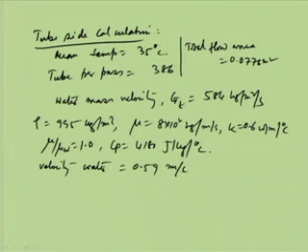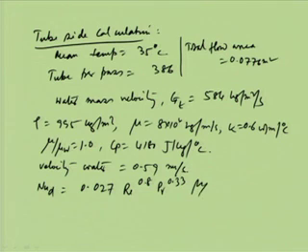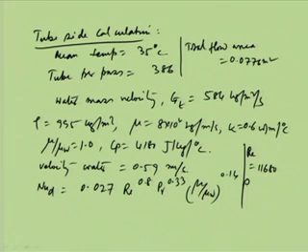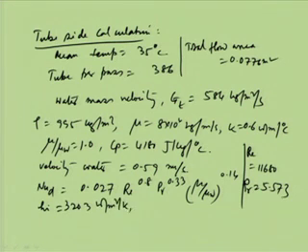0.59 meter per second, and then using the Sieder-Tate equation, Nusselt number we know, as we have done, 0.027 Reynolds to the power 0.8, Prandtl to the power 0.33, mu by mu W to the power 0.14, and here I have Reynolds is equal to 11680, and Prandtl number is equal to 5.573, and from there we can calculate HI is equal to 3203 watt per meter square per Kelvin, and HIO is equal to HI into ID by OD, and this gives me 2562 watt per meter square per Kelvin.